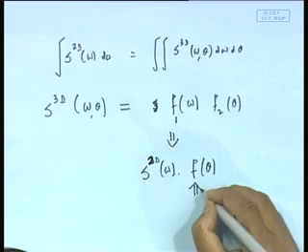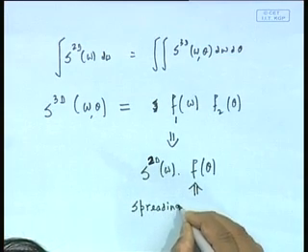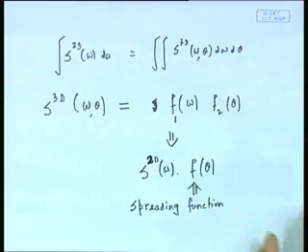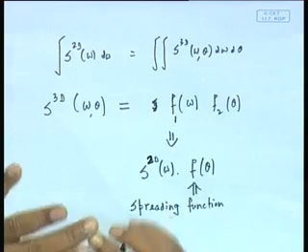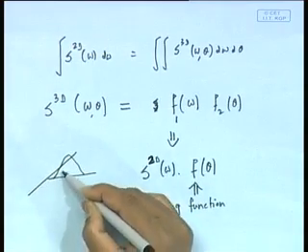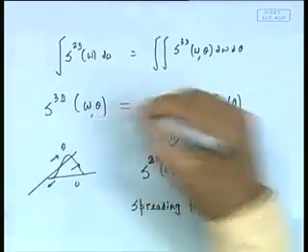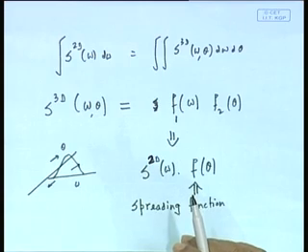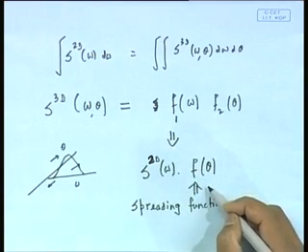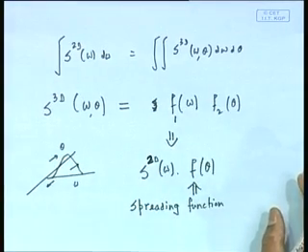This is known as the spreading function. You can easily see why it is called that, because we have taken S2d. If I were to now look at this side, this is my omega, I have done the S2d part here and I simply spread it this side, this is the theta side, by multiplying it with a function and tapering it down. That gives me spreading. For example, if f theta was 1, then it will be equally spread, meaning there is an equal chance of waves coming from all directions.